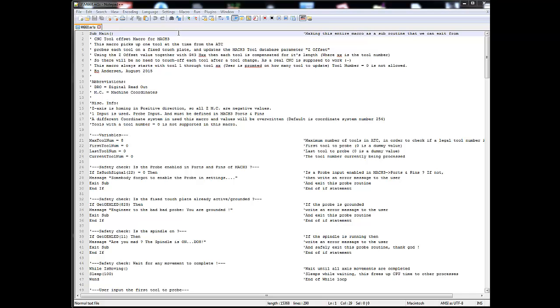I just wanted to go through a subprogram that I've written for MACH3, a script that essentially picks up a number of tools from my automatic tool changer and probes them twice on a fixed touch plate, and writes the offset of the tool length inside the database. So I'll try to go through the program. There's another video where I show how it's actually performing on the machine itself. So these videos complement each other and vice versa.